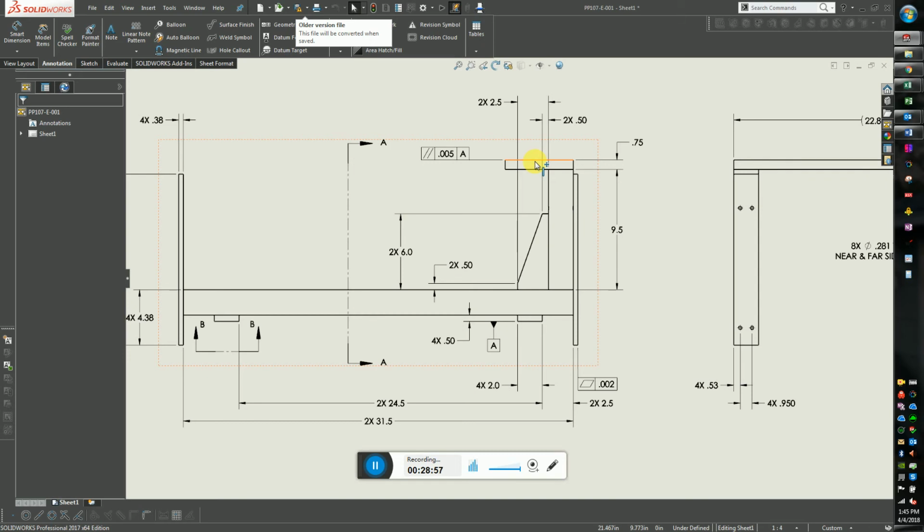Now, granted, sometimes you put these things on drawings and you get it back, and it's like, oh, this just isn't to print. And then when it comes down to it, you hold the machine shop accountable, rather than if you didn't put that on there and now your machine's sitting like this. Well, now whose fault is that? You didn't put any sort of tolerance or dimension on that to constrain that. So, like I said, it's a CYA type of thing. Yeah, well, that's kind of what my original question was. If you understand how to use it, there's definitely value in using it. Take advantage of it. Yes, absolutely.